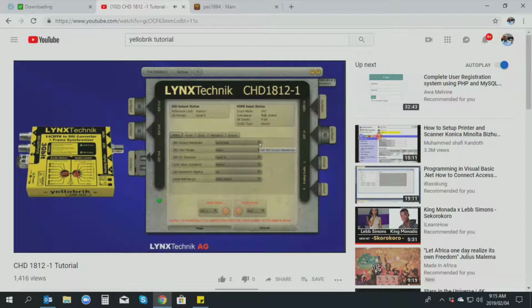Another thing that happens is if you do ever change any of the internal settings away from the factory reset values, this LED turns an amber or yellow color. So what it's letting you know physically on the module is there are some internal settings within the module in software that are different, that I may not be aware of, to factory standards. If the module's doing something stupid, or if you don't understand what's going on, and you see an amber LED there, you can connect up the software and do a factory reset or see what's different. Or you can connect that little factory reset button in through the hole, and that will reset the module back to factory, and the LED will turn back to green.